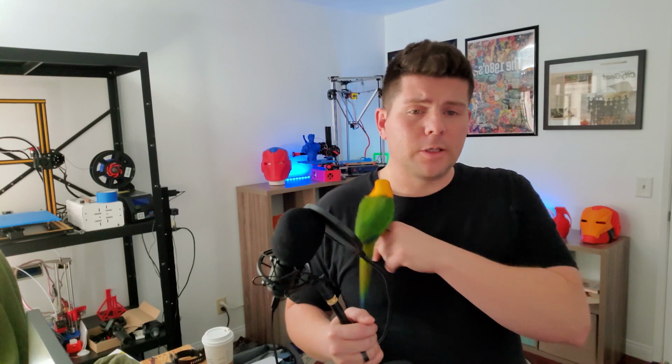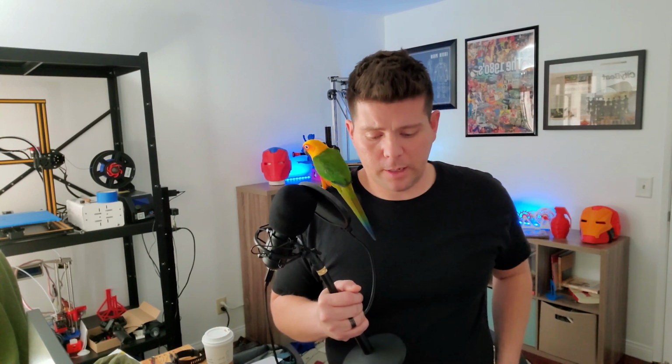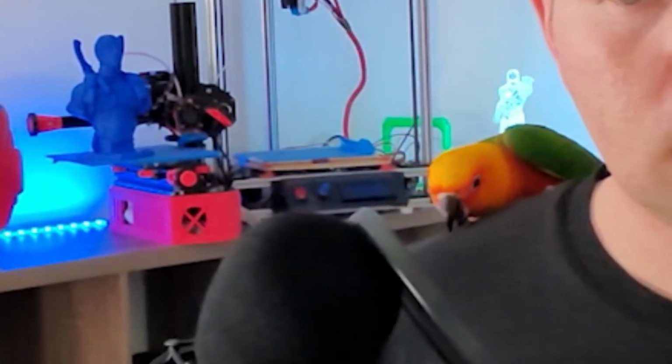So what I like to use is a CAD program called Fusion 360. Many of you have heard about it. You can get it from Autodesk, and they have a maker and hobbyist / educator's license. You can use it for free. So what I used to do was download it from their site as a STEP file into Fusion 360 and then export as a high-res STL to my local slicing program.